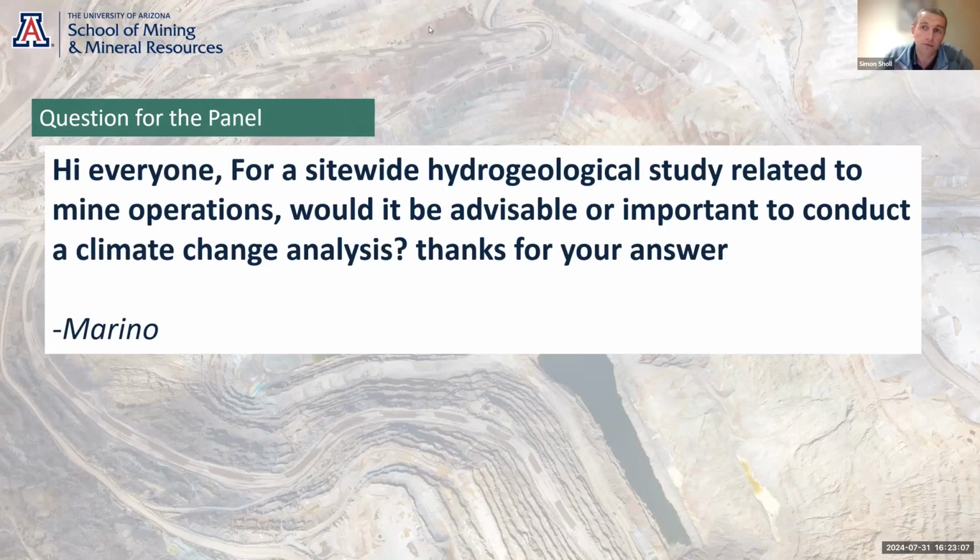I would say really for a lot of closure studies, you'd be better off looking at a sensible sensitivity analysis to understand the range in which your groundwater levels, flows, and so on might change.